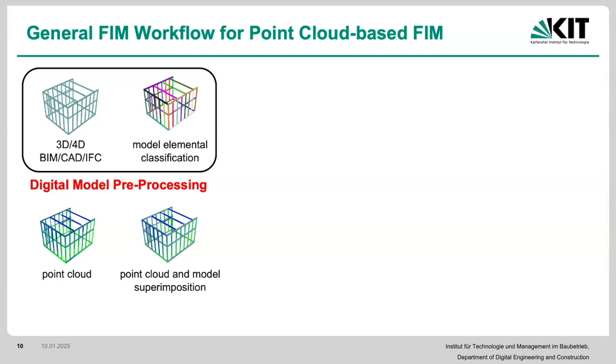Can I say that I'm just going to be taking the points of different vertices of this column from the model and the point cloud and then register them together? Would this be a correct registration? Keep in mind that this column is not supposed to be here based on our plan.